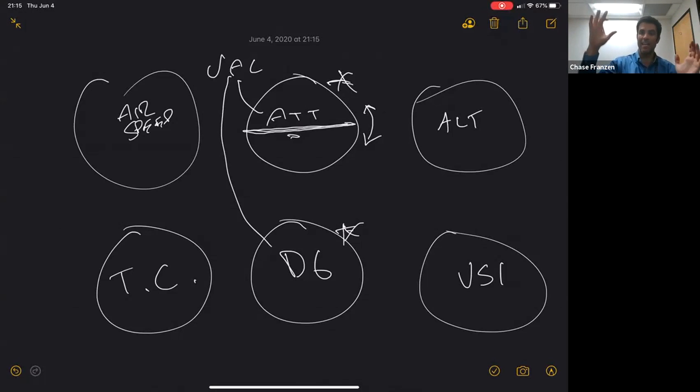Similarly, just like left and right bank, if you pitch, that gyro wants to maintain level to the ground, so you end up moving the instrument up and down, or pitching it forward and backwards, relative to that thing spinning inside of there. It would be just like if I took my bike tire off of my bike and had you hold both sides of the hub on the quick release skewer, and I spun it real fast. You would have a difficult time doing this because of the principle of rigidity in space. So all the vacuum instrument is doing is spinning that disc inside of the instrument, and the instrument and the airplane as a whole ends up moving around that disc. Does that make sense? Very hard to explain without us physically being together.